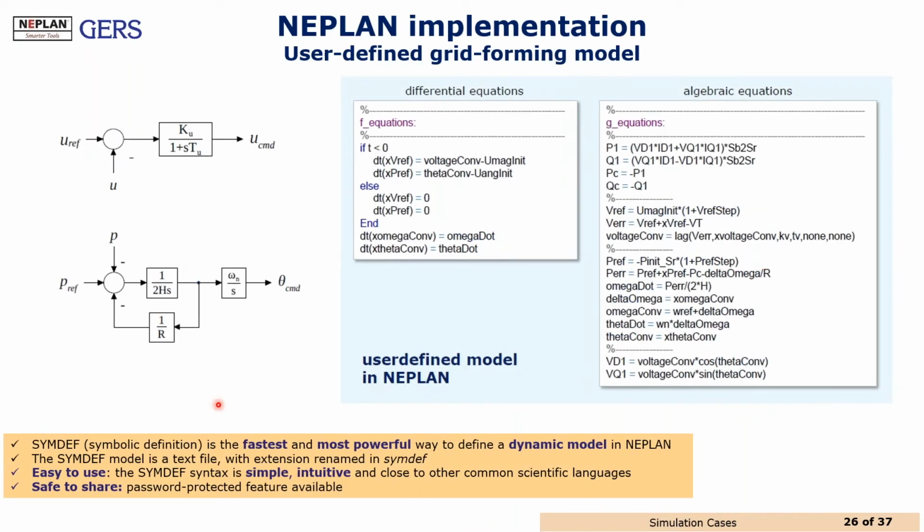SYNDEF is the symbolic definition, and this is the way to define dynamic models in NEPLAN. It's a text file with its own extension, SYNDEF, and allows to create user-defined models easily, and it is able to be shared with a password protected feature.